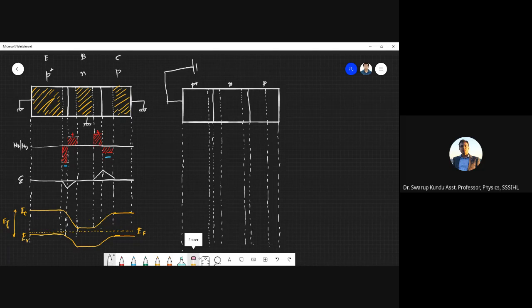So this will be positive, and the base junction, right? So this is forward bias. Now this other junction has to be reverse biased. So the N side has to be reverse biased, meaning the other side has to be positive, right?